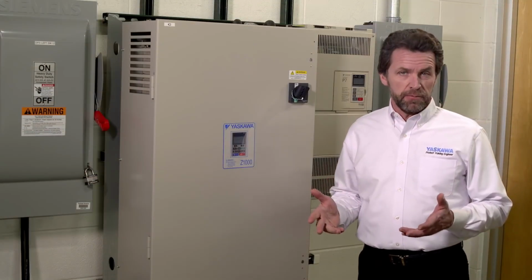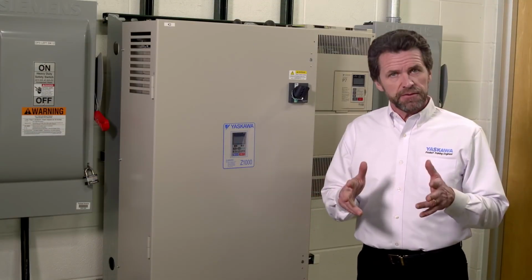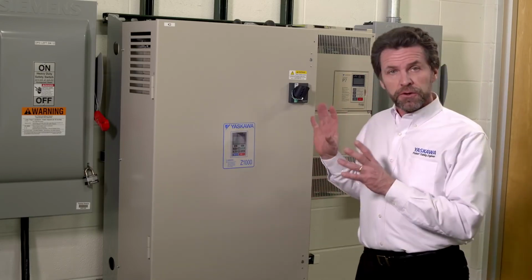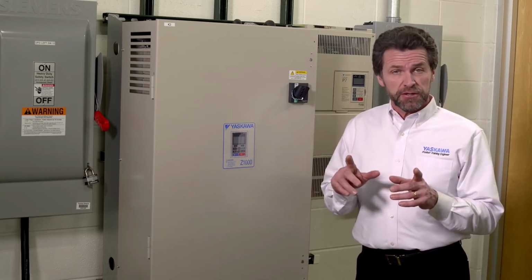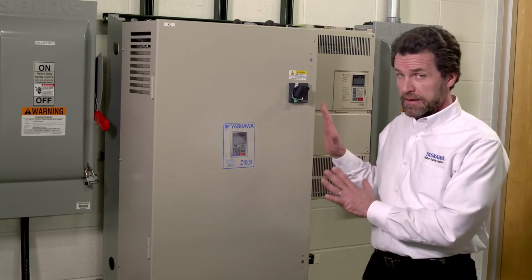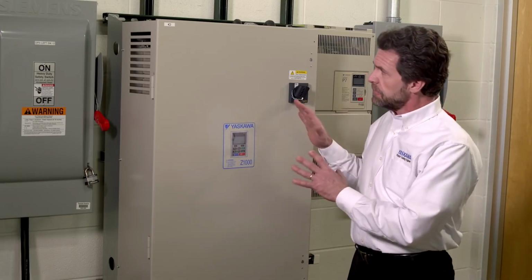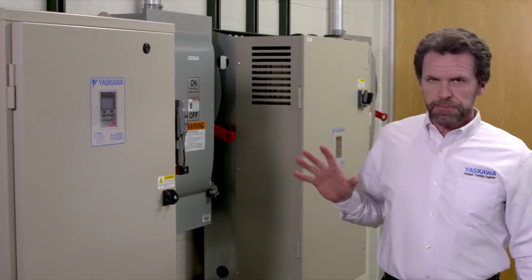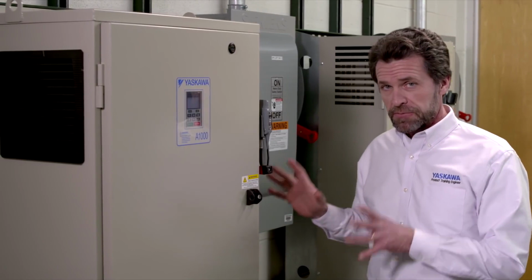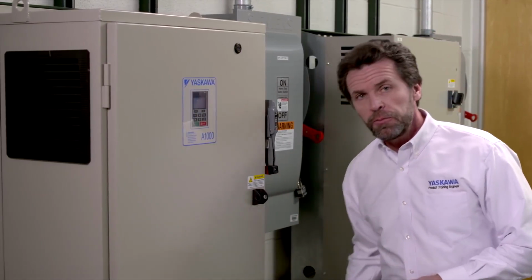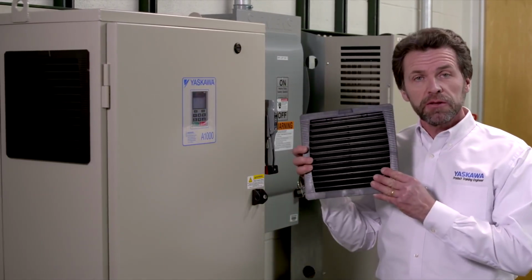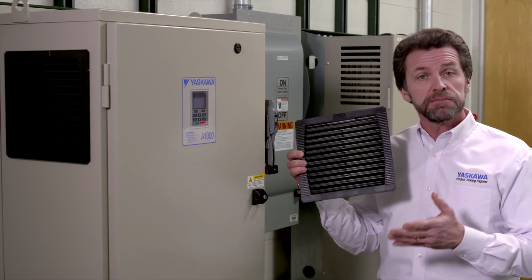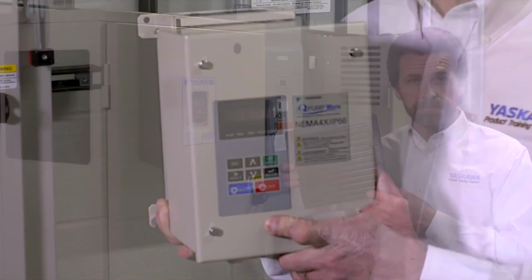Depending on the type of environment the system will be exposed to, the drive enclosures will vary. NEMA 1 enclosures are designed for indoor applications and provide protection against finger contact with live electrical components and a limited amount of falling debris. NEMA 12 steps up the protection. It's also designed for indoor applications, and all openings have filters that require regular maintenance. The filters protect against circulating dust, falling dirt, and non-corrosive dripping water.